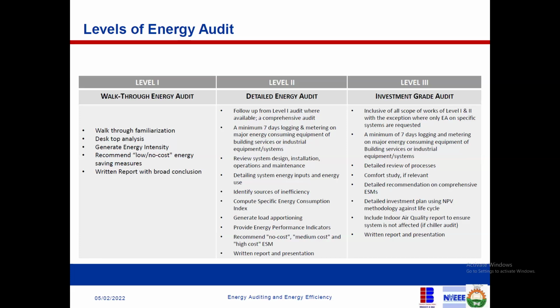Or you could do a no cost one. Not every energy recommendation has a cost component. You can also say, okay, from now henceforth, by 7 o'clock, all the security lights, external lights should be off. From now henceforth, during night hours, we should only do some of our major work during the day. During the night, when the solar is not on, we should do some kind of load shedding.